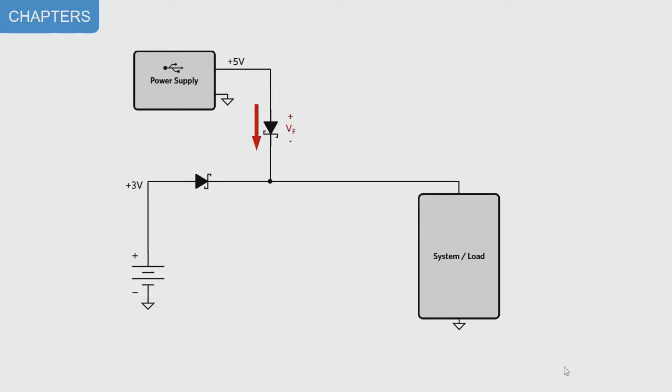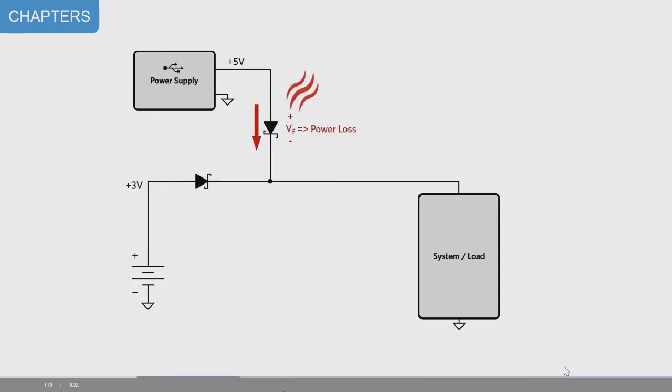First, their forward voltage, although lower than other diodes, still contributes to large power losses, which is lost as heat. For example, if a Schottky diode has a 300 millivolt forward voltage and is supplying a 3.3 volt rail, there is a constant 10% power loss in the diode alone. When operating from a battery in a tiny device, power loss and heat should be minimized at all costs.